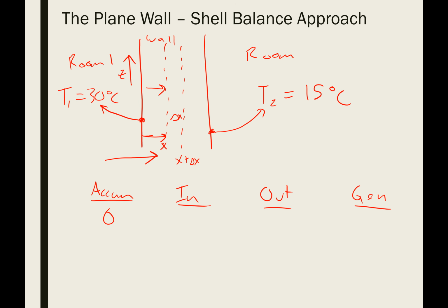All right, so we go back to our energy balance. We have generation is 0, mainly because we're told that. Generation is more the exception than the rule. Okay, so into this little slice, this imaginary slice that we've taken from the middle of the wall, again, it's not exposed to either edge, it's embedded right in the middle of the wall. How is energy getting in? Which mode of heat transfer? All right, so energy is getting in by conduction, and it's getting out by conduction as well.